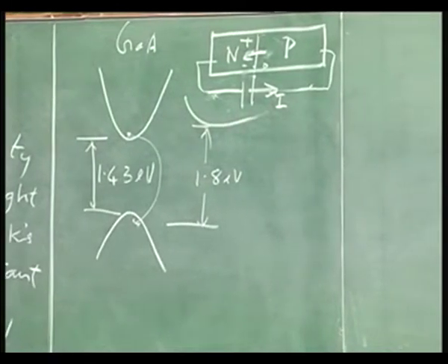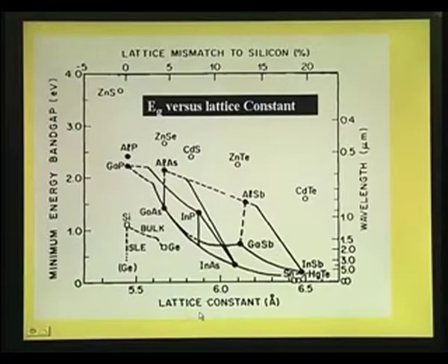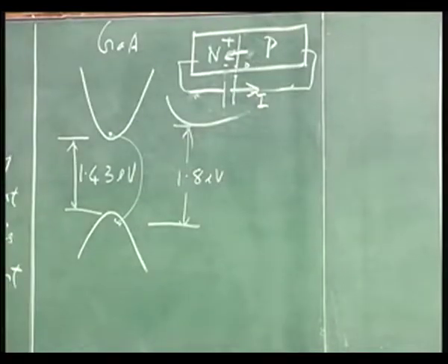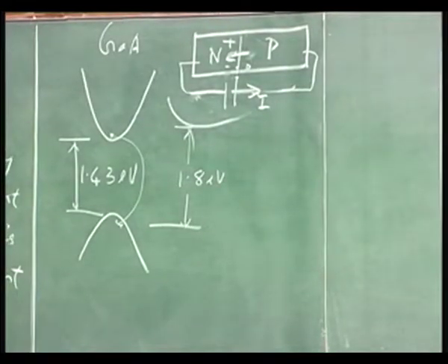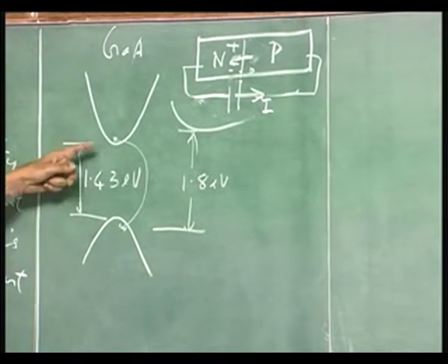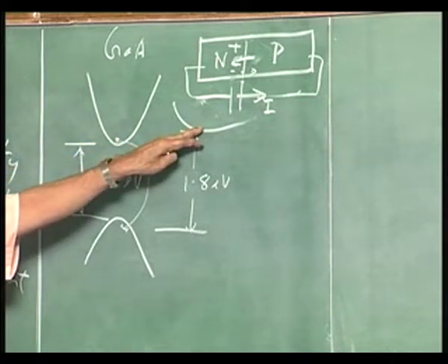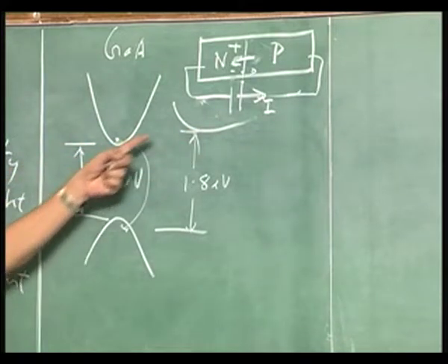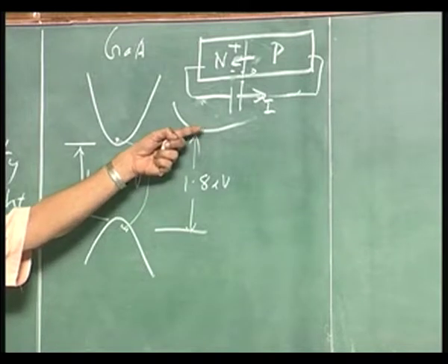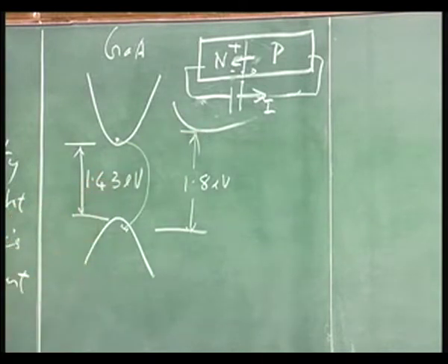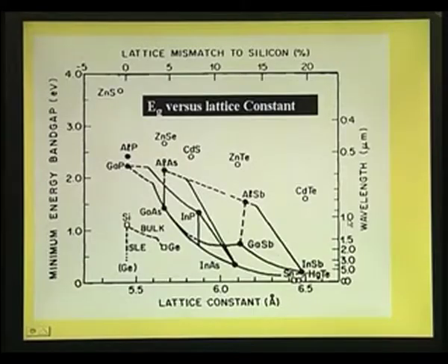So, let us see, this diagram that you have drawn is actually a diagram for gallium arsenide direct band gap, and also we have said the minimum band gap that is put there implies that this is the minimum compared to that. If you transfer the electrons from here to here, if they were there, then it would have been an indirect transition. I am just trying to point out some of these things which are in this diagram. So, on this side you get that wavelength which is 1.24 divided by energy.